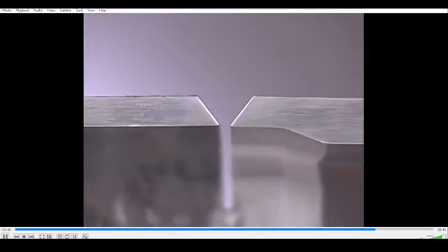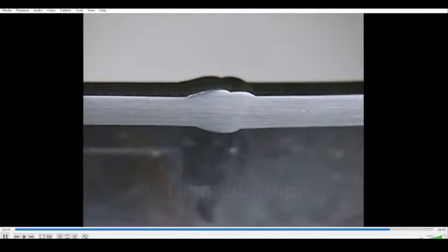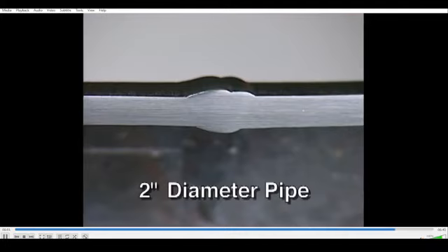At times, it may be necessary to weld 2 pipe sections with different wall thicknesses. In this case, a specialized kind of joint called a transition joint is normally prepared. The thicker of the 2 members is machined down to match the thickness of the thinner member before reaching the joint edge. Usually, thinner materials or small diameter pipe and tubes are welded with the gas tungsten arc process alone.